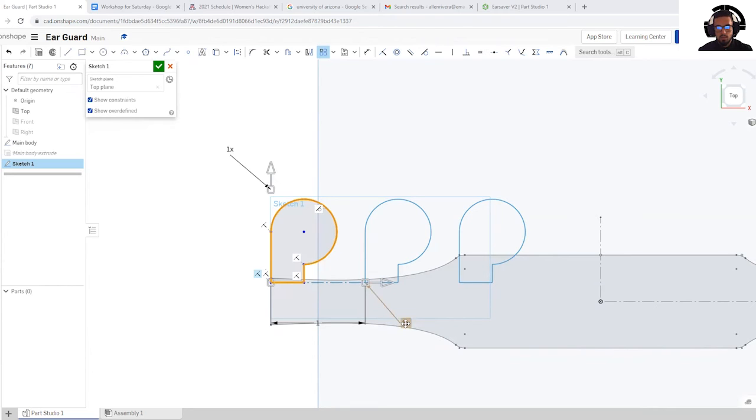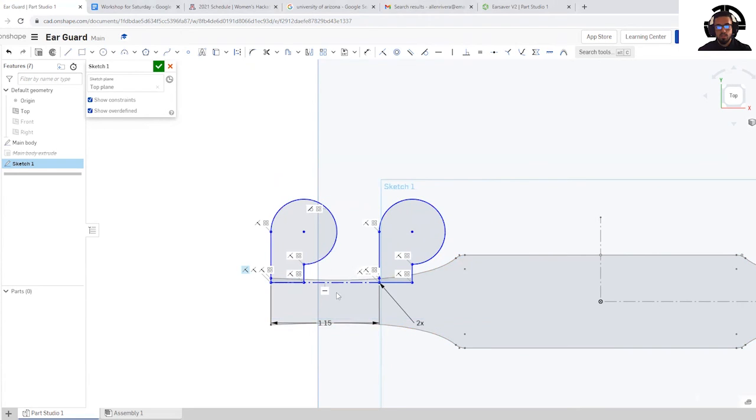So I actually want 2 for now, right? So I'm going to click right there. I'm going to hit 2, double click right there and hit 2, hit enter. And now I have 2 objects and I can set the distance that they're going to be at. So I can change that distance by either dragging it or I can change the distance by setting it equal to, let's say, 1.115 inches. And that looks just about good to me. So I'm going to left click out of it, and now I have 2 objects.